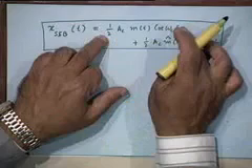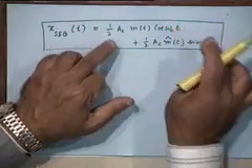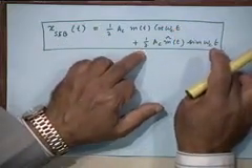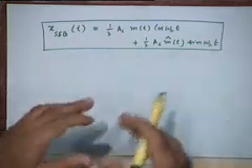It's not easy to visualize this waveform, because to visualize this waveform you not only have to visualize this plus but also you have to visualize this. Now for an arbitrary signal one doesn't know what m hat t will look like. For a certain kind of signals one can work it out. For example, for cosine omega mt I can say that the Hilbert transform is sine omega mt, right?